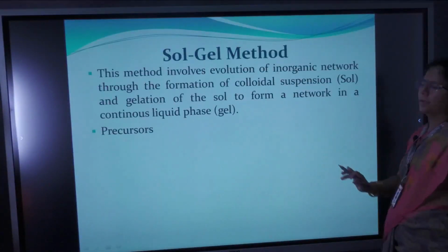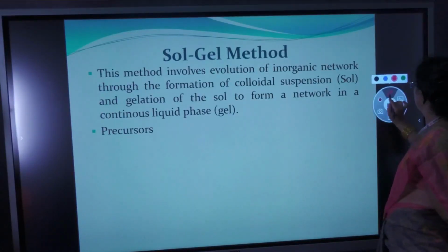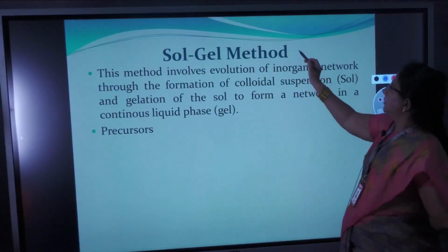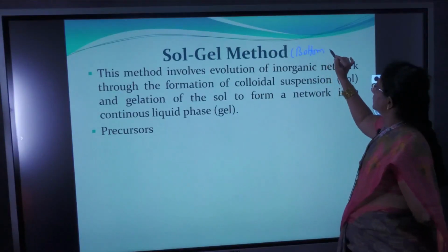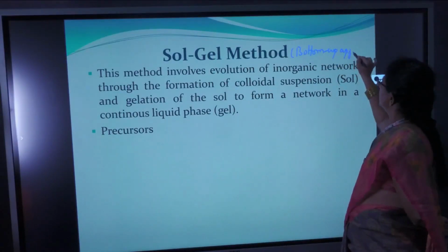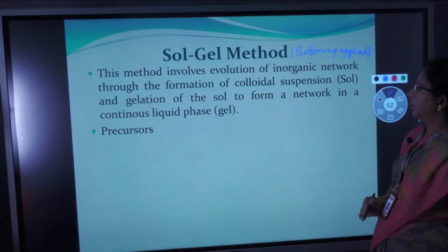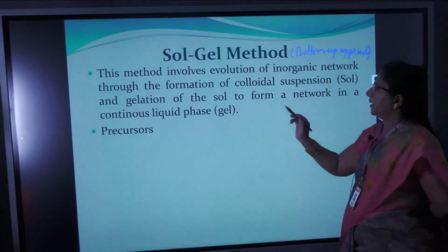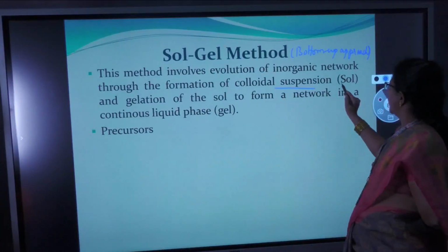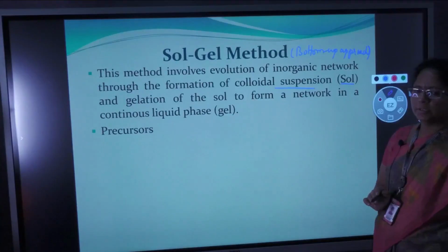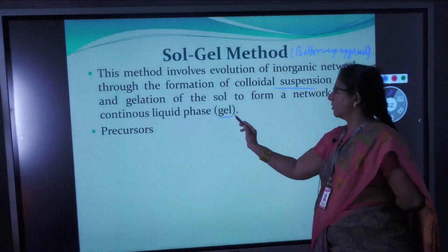Now coming to the sol-gel method. The sol-gel method comes under the bottom-up approach. This method involves evolution of an inorganic network through the formation of a colloidal suspension, that is nothing but sol, and gelation of the sol to form a network in a continuous liquid form, that is called gel.